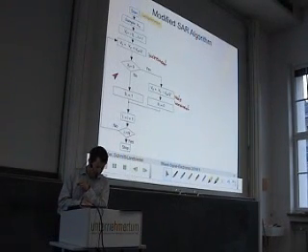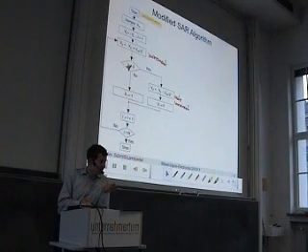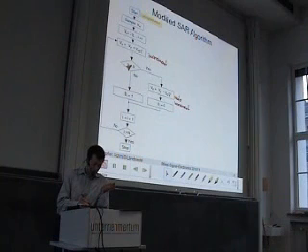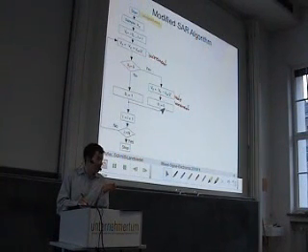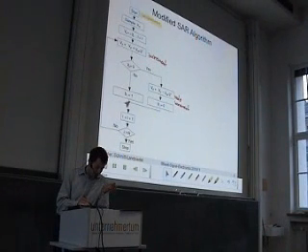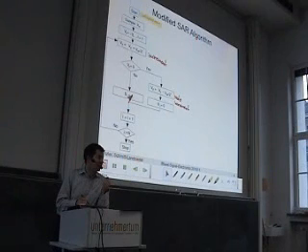And in the next cycle, again, we increment the Vx now by a smaller increment. We check for the sign. If the value that should be negative is now positive, then the increment was too large. We undo it and set the respective bit to 0. If it is still negative, then we keep this increment and we set the respective bit to 1.